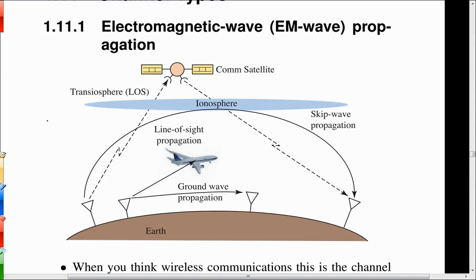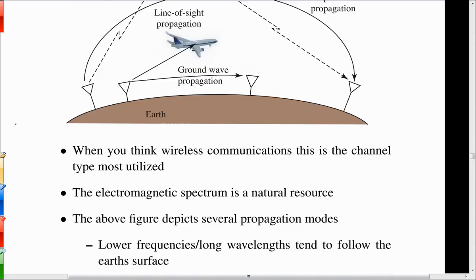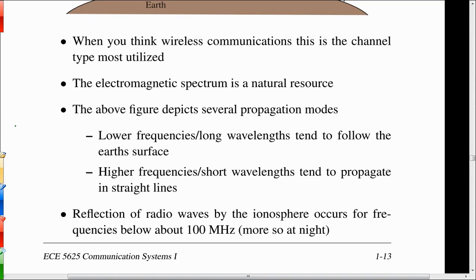But this is a crossover region for comms people. There are great propagation theory books. All I know is the simple model is just to say the ions act like forming a metal-like screen. So signals above a certain frequency will pass through the ionosphere, and those that are below, say 100 megahertz, are not going to get through the ionosphere.